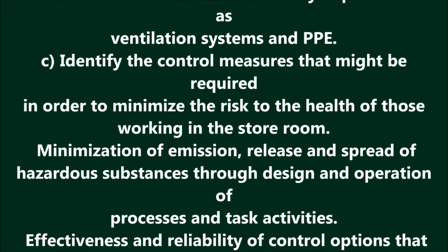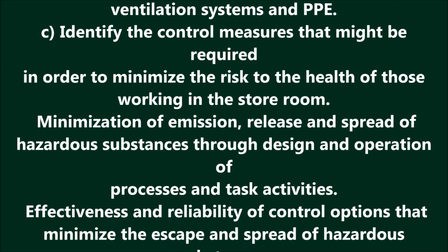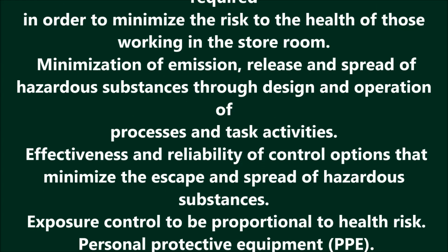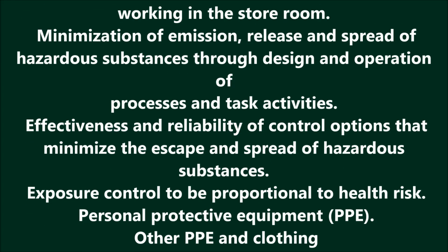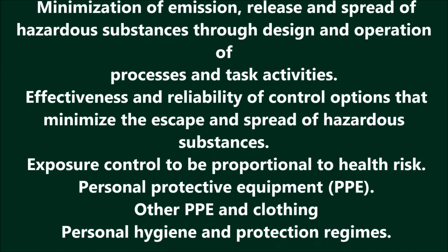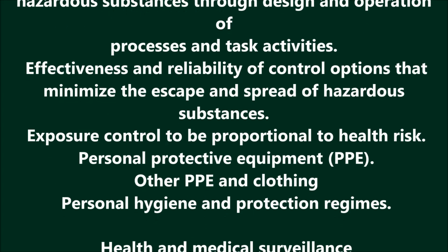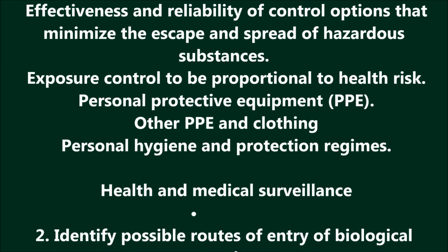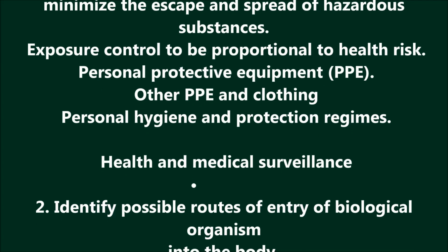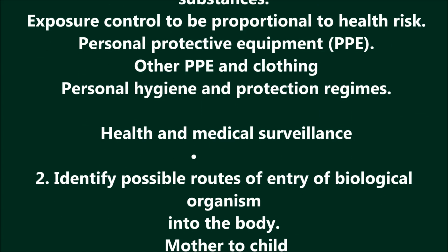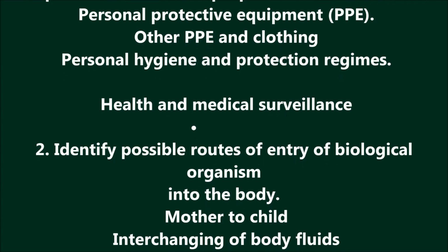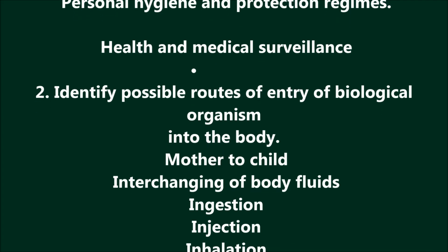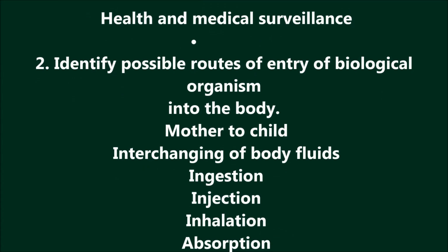C. Identify the control measures that might be required in order to minimize the risk to the health of those working in the storeroom. Minimization of emission, release and spread of hazardous substances through design and operation of processes and task activities. Effectiveness and reliability of control options that minimize the escape and spread of hazardous substances. Exposure control to be proportional to health risk. Personal protective equipment, PPE. Other PPE and clothing. Personal hygiene and protection regimes. Health and medical surveillance.